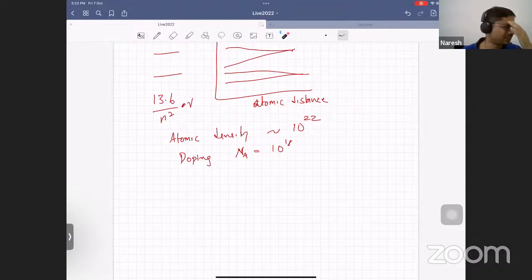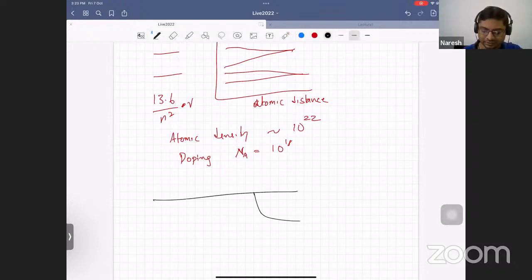There are a couple of those, and what is the other one? Float zone, right? There are techniques that actually dope it, but you do that only when you are preparing the substrate. But then, for example, if you want to make a MOSFET, you have N plus and P, right? How will we get this? This sort of thing is achieved by what is known as implantation.